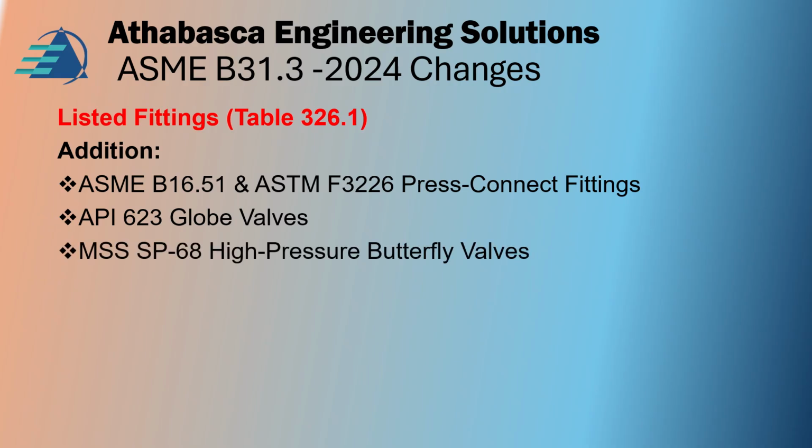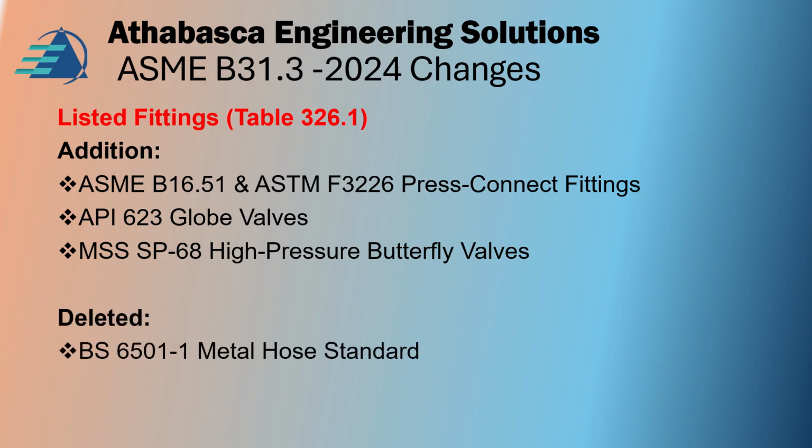The other one is MSS SP-68 high pressure butterfly valves. And what's been deleted is BS 6501-1 metal hose standards. So they've made a number of changes and realignments to the different standards and different criteria. And some jurisdictions like TSSA in Ontario have even more to say about the design requirements for the hoses. And that's all to do with safety.